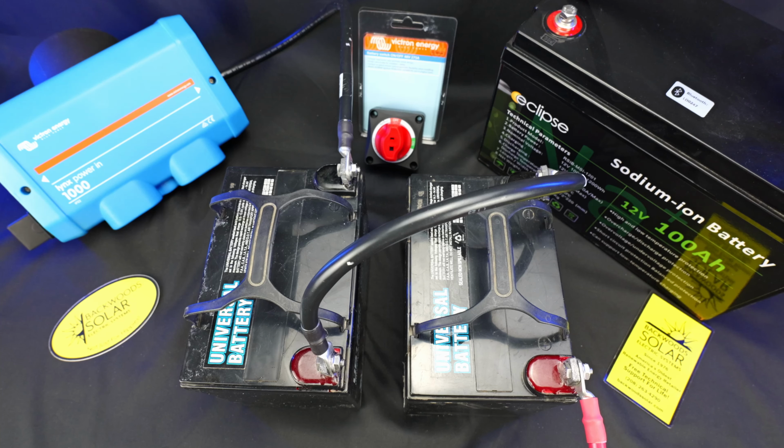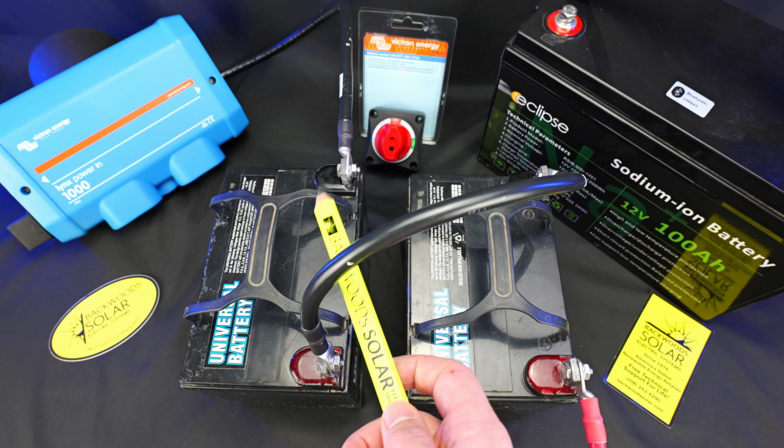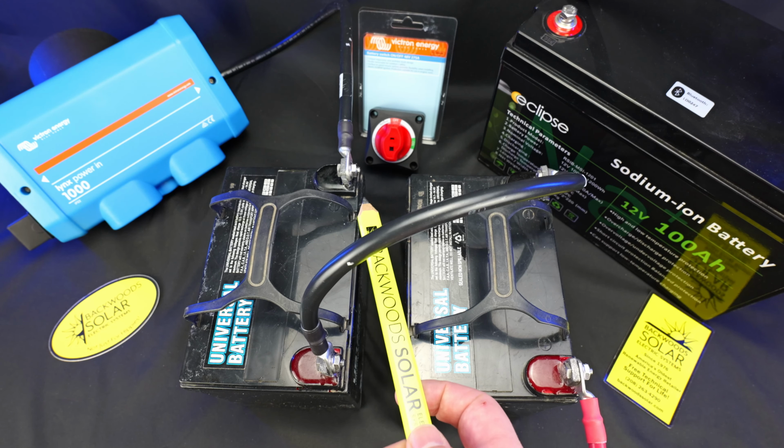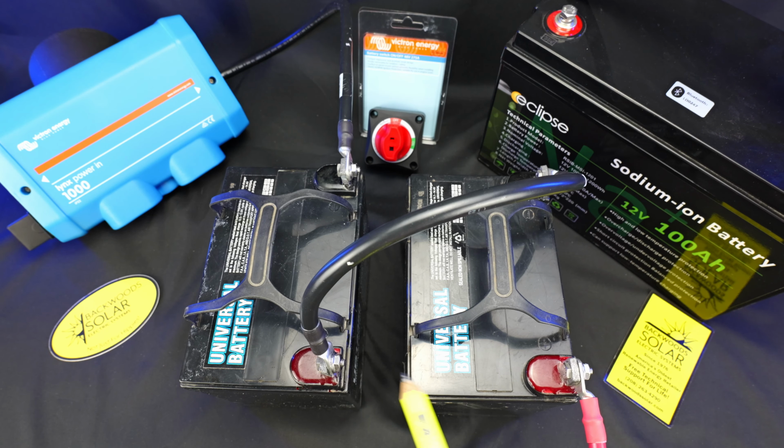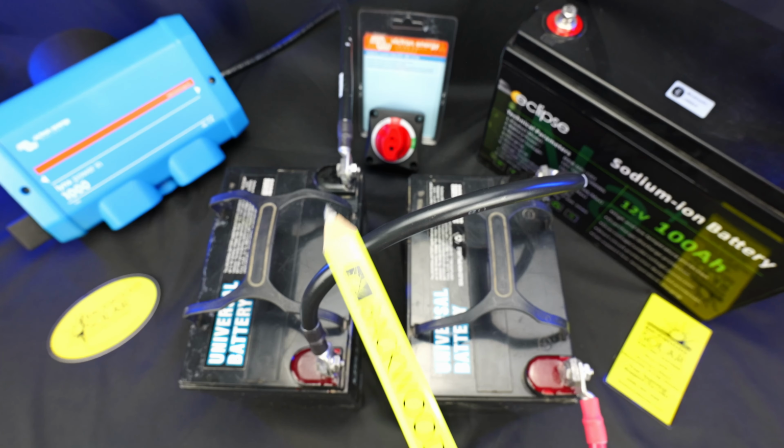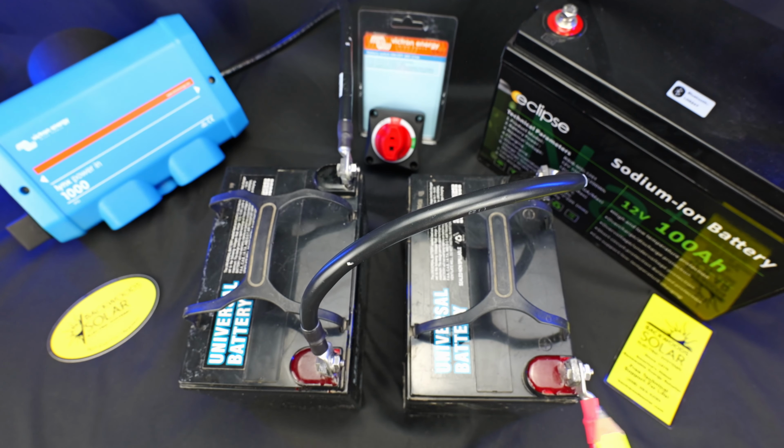Beyond the specific recommendations as noted by the manufacturers, I just want to mention a couple general recommendations for your battery bank and long-term health. Number one, on both lead and lithium batteries, I think it's important after some time period, a couple weeks, a month, a couple months, to come back and recheck our connections for tightness. This is important, again, especially with lithium, given the low internal resistance. We want to make sure all our connection points are as equal resistance and tightness as we can.